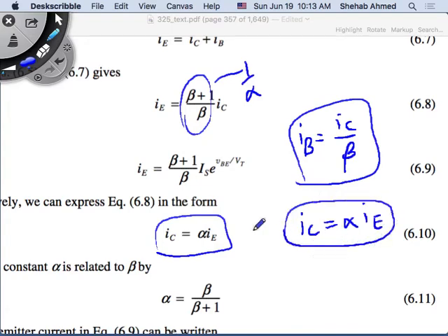It makes sense because they're all diodes, the same diode with the same saturation current, assuming the areas and the concentrations are the same. Since they are not the same, there's a scaling factor that relates the different diode currents. So I have different diode currents that are related by the variable beta.